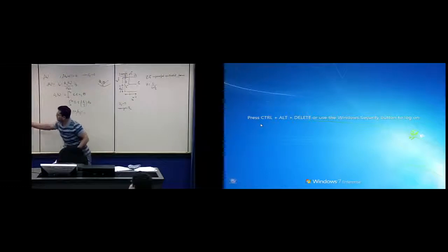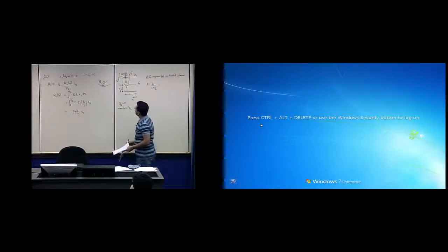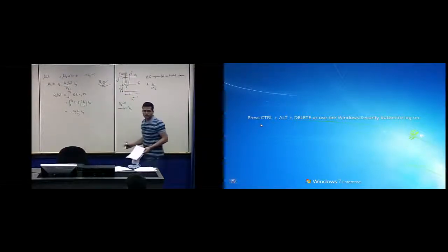So if we calculate the shear flow or the shear stress in this segment at this location, this is my 1 and this is my 2, I have the shear stress here in this segment evaluated using the expression which we calculated here for the first segment. Then I can say that my shear stress in the segment 2 at that location when S2 is 0 should be the same, right? Because of reciprocity.